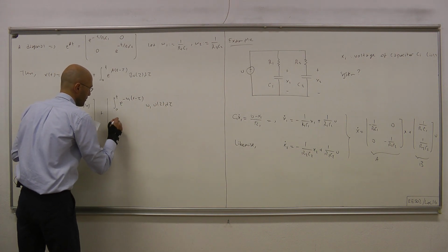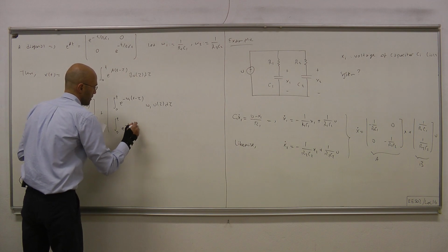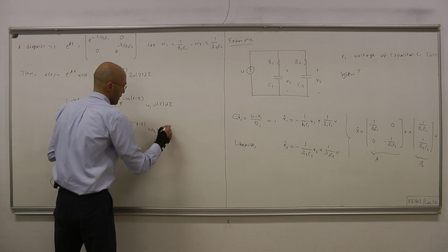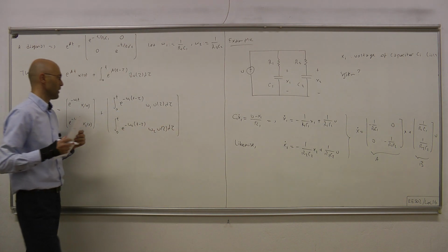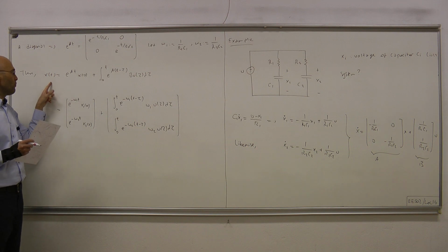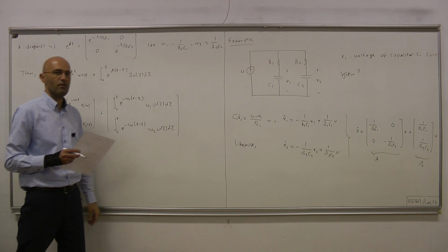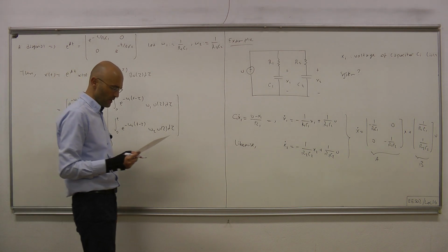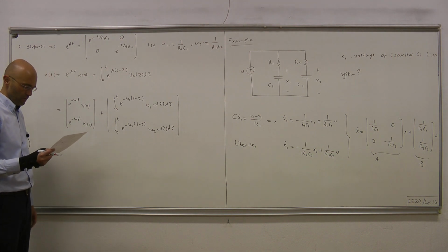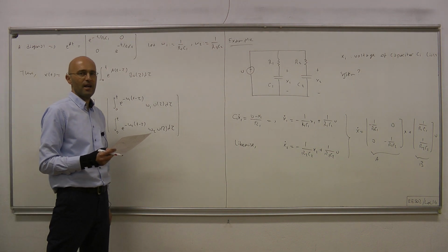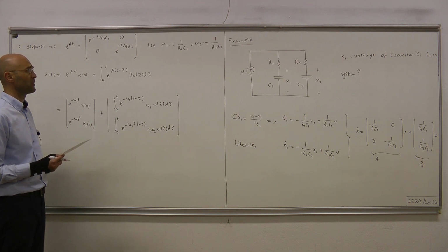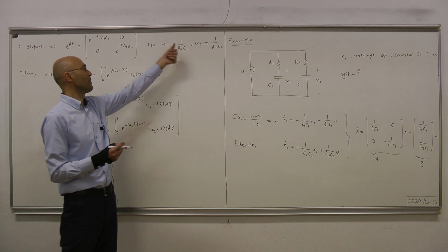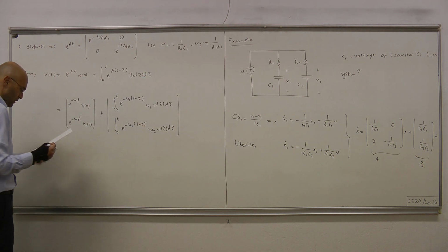And the second term, likewise, e to the minus omega 2 (t minus tau), omega 2 u(tau) d tau. Now we have the full expression for x of t in terms of our system parameters, and now we can determine the reachable and controllable subspaces. Now we're not going to make the general analysis. Let's concentrate on this special case where the time constants are equal, R1C1 equals R2C2, or omega 1 equals omega 2.